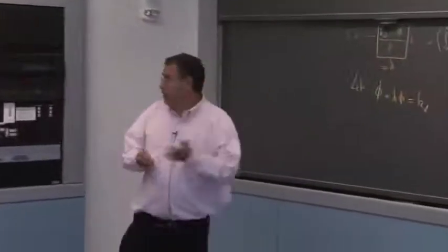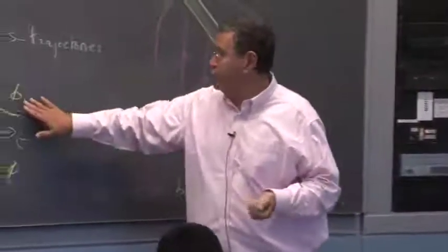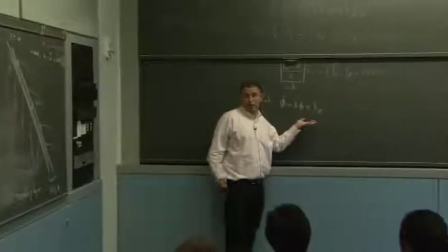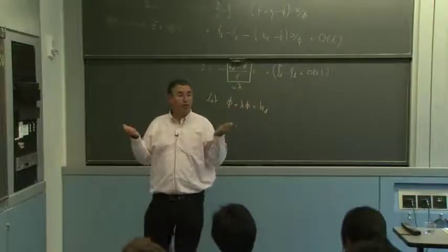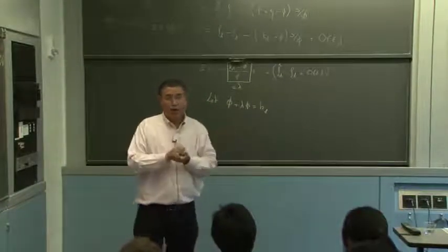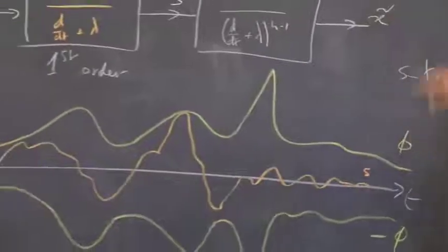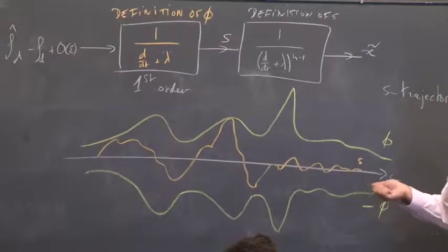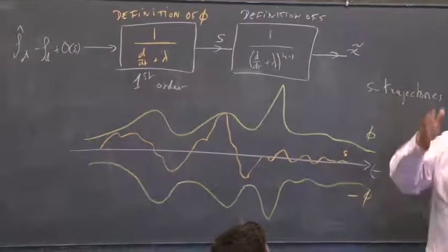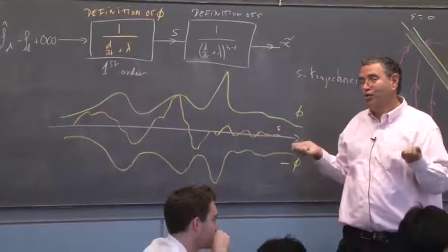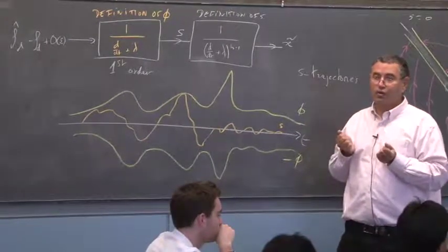And of course, implicitly, this also says phi is a filtered version of KD, right? So it's simply a fast filtered version of the uncertainty as a function of time, as a function of where you happen to be in the desired state. Right? So it also tells you that, okay? And suppose you have a rather common motion and phi itself is all over the place, it means you're not doing a very good job at modeling, because half of the time phi is huge and half of the time it's really small on a normal operation, which means your modeling was very uneven.